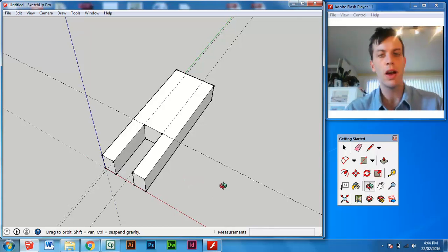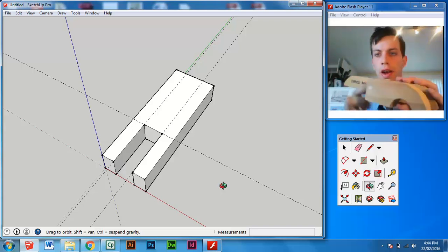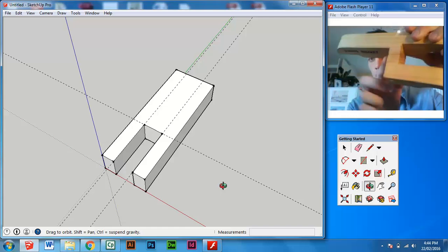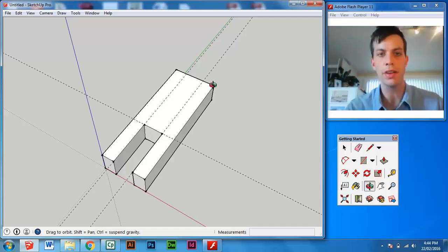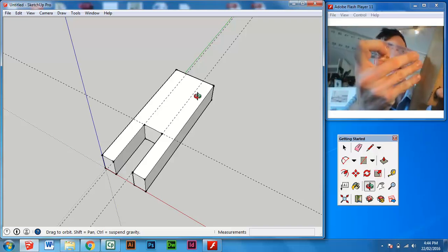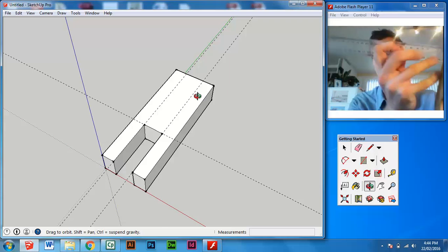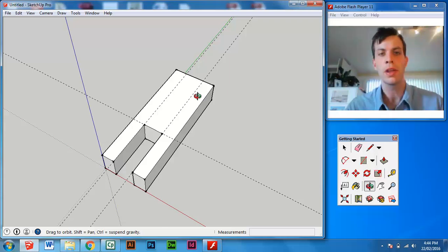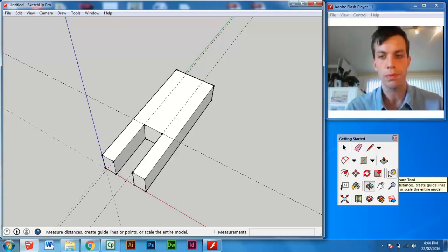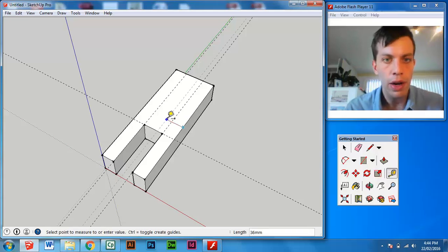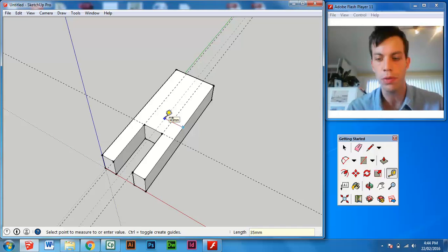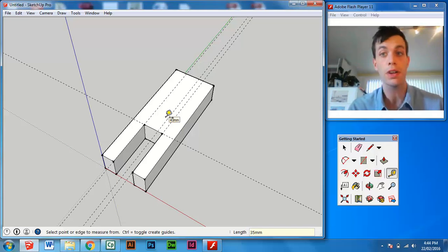So now I've got the front of the fork here, and I want to get the back of the fork now, this bit here, to try and get rid of all of this shape here, because at the moment it's still very full there. If I measure across on this bit, it comes to 35 millimeters. That's 35 millimeters thick there. So once again, I want to get my ruler, and click on the corner, and go to about there, and then I type in 35 millimeters. It's much easier to just type it in every time rather than worrying about getting it perfect with your mouse.